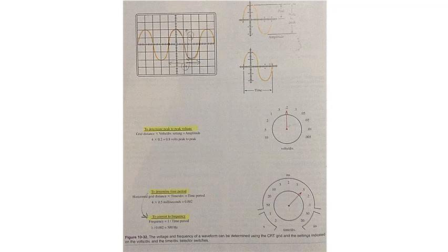Voltage measurement. To measure the voltage of the wave displayed on the screen, simply use the grid as you would a common ruler. If the voltage selector switch, usually marked volts/div or volts/cm, is set on 0.2, then the distance across each grid square from top to bottom is equal to 0.2 volts. If the volts/div is set to 0.005, then the same grid space is equal to 5 millivolts.